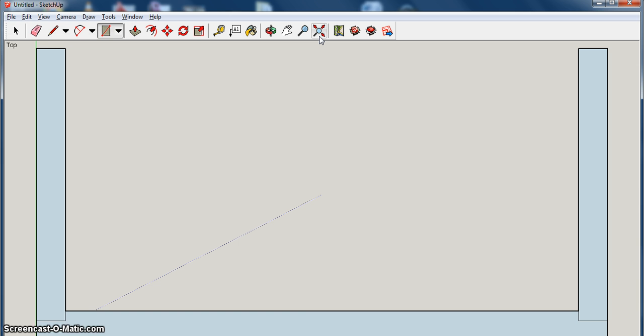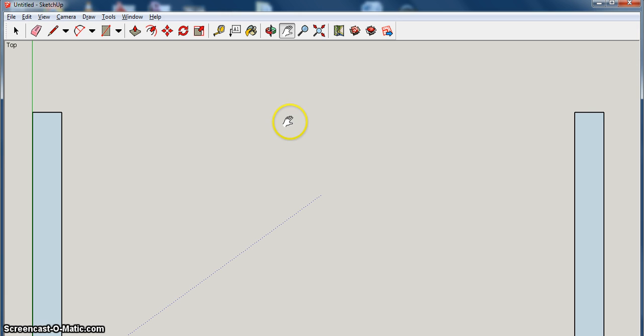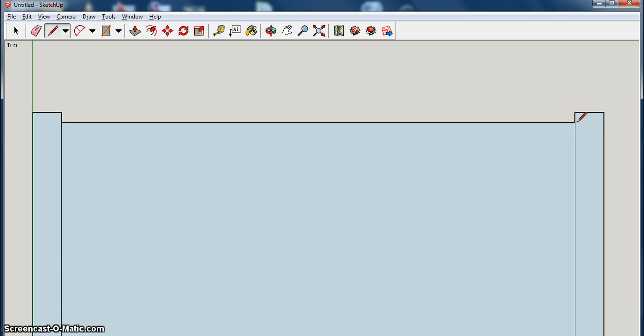Now from there, the other side of our pencil box is a little bit trickier. And I'm going to use my pan tool to bring that down a little bit. So I know that my rebate will come in 4 millimeters and then my piece will come along. So I'm going to draw that particular section in first. So from the edge, I'm going to come down 4, enter, again pick up that green line, bring that all the way along, waiting for it to change colour.